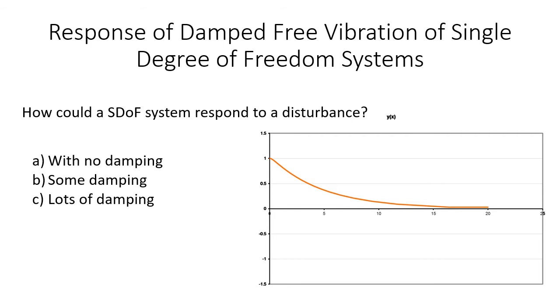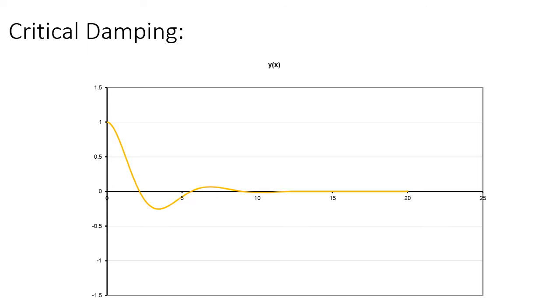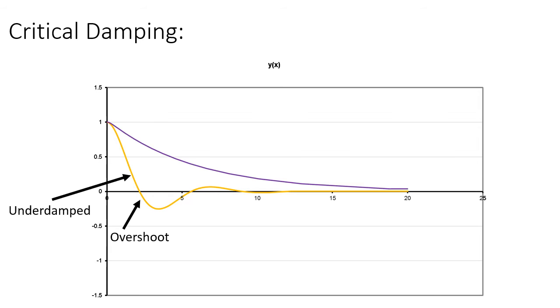of response. If we've got a little bit of oscillation, then we get an overshoot from the neutral position, and we will call that system an underdamped system. If we increase the damping to the point where we get this sluggish response, there's no overshoot, we would call that an overdamped system.